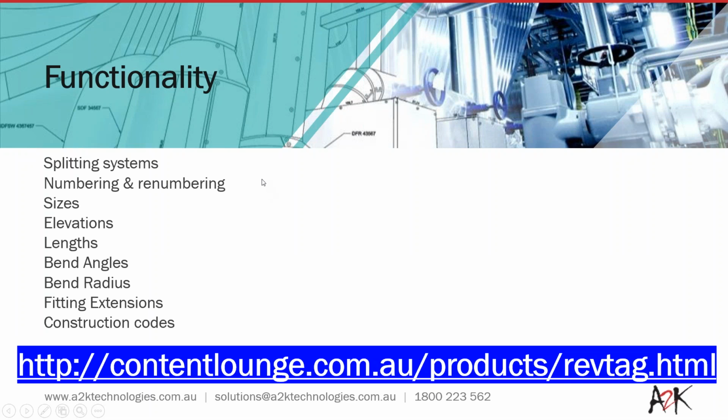So the functionality moving on for the Revit Tag Tool is we've given you the option to split Revit systems, duct and or pipe systems, a numbering and renumbering function, sizing, elevation tagging, length tagging, bend angles, bend radius, as you can see in this list, fitting extensions and construction codes.